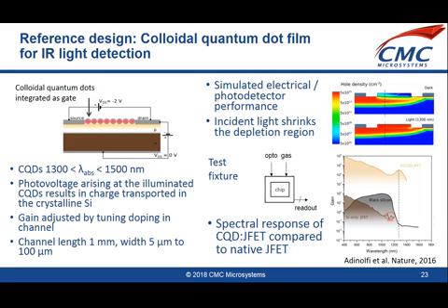This was simulated in the Centaurus device environment, first of all, and two of those simulations, including their source code, are bundled with the reference design and are available to designers as part of the design kit. And finally, on the bottom right of this slide, the spectral response of the device as measured by the designer is shown. And you can see that the photocurrent as a function of light wavelength shows both what is native to the silicon-only JFET and then what is achieved as a result of integrating quantum dots directly onto the JFET surface.